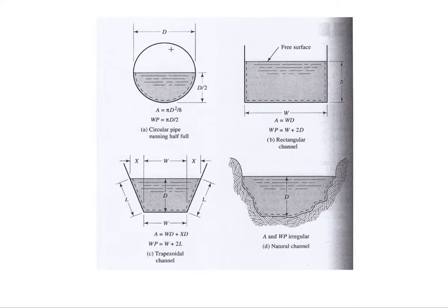Okay, let's say we have a circular pipe here, but the water level is half of it, like this. Here the atmospheric pressure acts on the surface, so this flow can be classified as open channel flow. Because the water fills half of this section, we cannot use diameter or radius only, because it does not reflect the real flow situation. But we need to calculate the hydraulic radius.